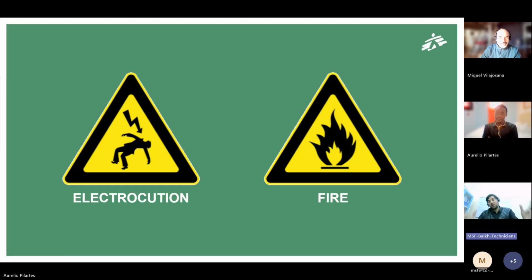some electrical devices like refrigerators, the cover is metal, and if the phase wire touches the metal cover, we don't know that the cover is already connected with the phase. It means indirectly it has power. So if somebody touches that, they get electrocuted. So for protecting against electrocution, for touching the metal case, we have the grounding system as a safety measure, and also for touching open wires directly